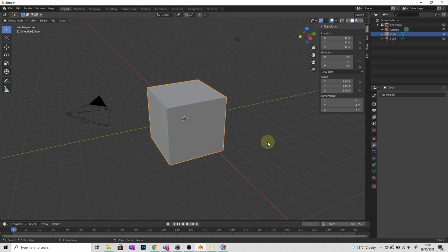I think what's also important to mention at this point is that I've been working in meters. What if you're working off a ground plan and it's in millimeters? You don't want to waste time converting those measurements. Even with your basic transformations, it's going to slow you down. What you then want to do is go into your scene properties, which is this little icon here with the cone and the little circle next to it.